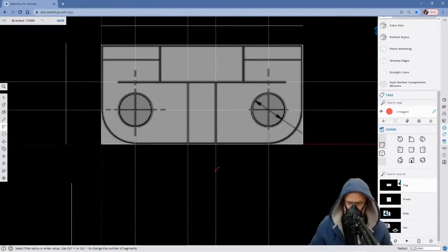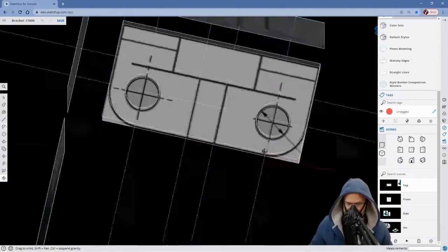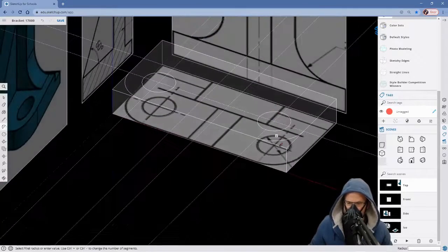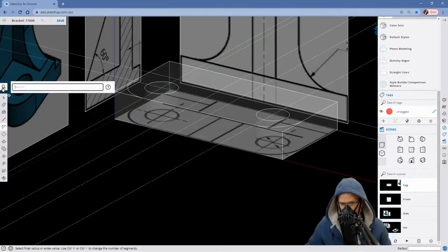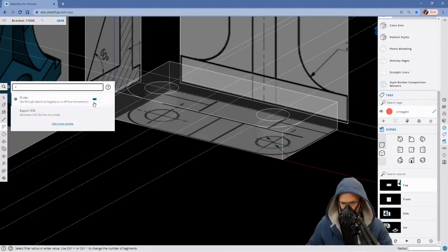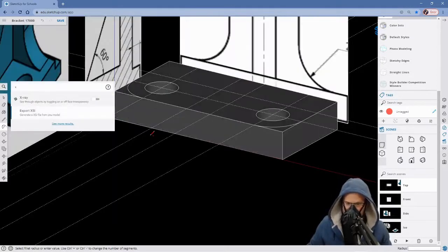Oh, very nice. Let's see if we can get the same sort of pattern over here. Intersection, intersection, tangent, and tangent again. Oh, that worked out swimmingly. All right, let's see if we can push-pull. I like to do the push-pull when I'm not in X-ray mode.